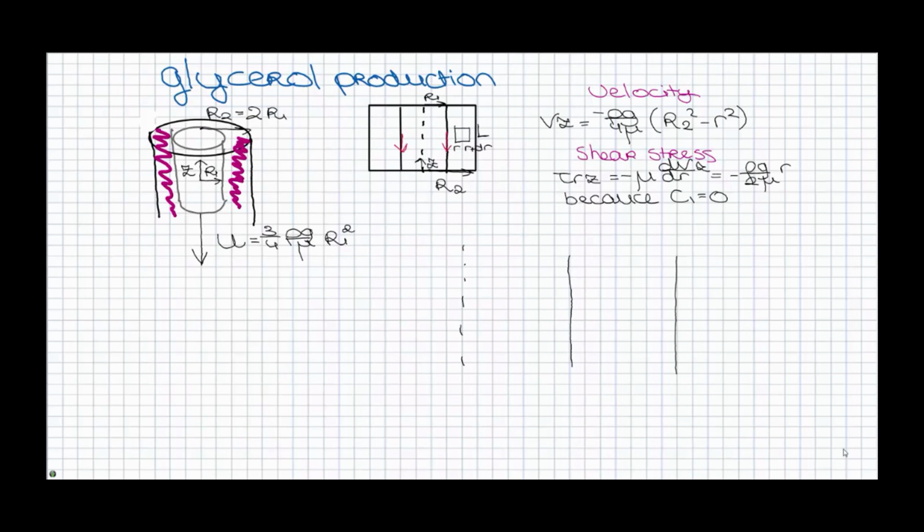As you can see, the points where the radius is 0, r1 and r2 are written down in the sketch. The boundary conditions say that at radius r1 the velocity is the negative version of u, and at r2 the velocity is 0. Furthermore, you can see that the equation for the velocity is parabolic, so the velocity profile needs to be something like this.